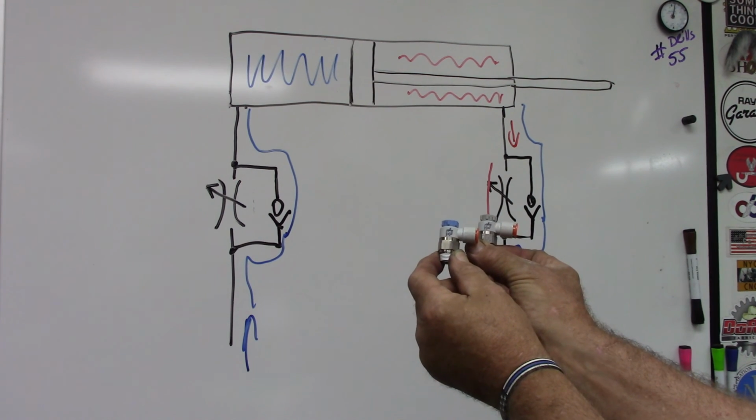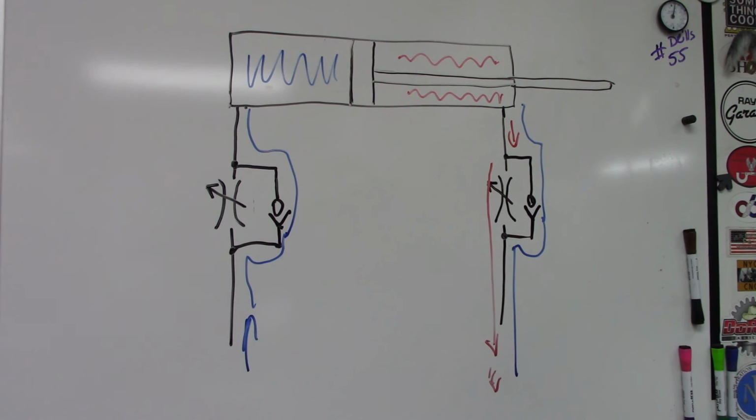Make sure you take a good hard look at those. Make sure you know what you're doing. Either one will work. But if you want a nice fluid motion, meter out. So that's my tip of the day. When in doubt, meter out.